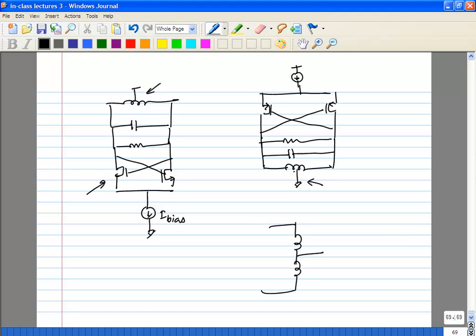Obviously that is better than using two separate inductors, in terms of area first of all. And then what you'll find is, in terms of inductance and coupling and so on, it's also better. This capacitance is a combination of fixed and variable capacitance. Remember, right now we are looking at oscillators. We have not gone to the voltage control part. So right now as far as oscillators are concerned, you just need an L and a C. This L is a design parameter, this C is not part of the inductor, it is a design parameter. You need to choose it large enough such that the inductor parasitic capacitances don't matter.